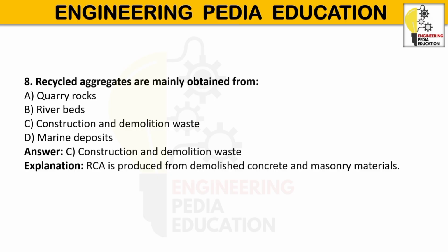Construction and demolition waste, commonly known also as C&D waste, refers to the waste material generated during the construction, renovation, repair or demolition of buildings, roads, bridges and other infrastructure. Proper management of this waste is important for environmental protection and sustainable development. Types of C&D waste: concrete and cement debris, brick masonry, wood and timber, steel and other metal, glass, asphalt, plastic, tiles and ceramic, soil excavation materials.